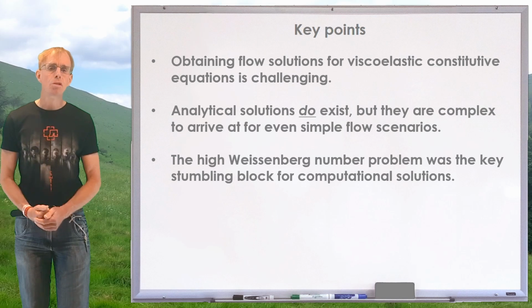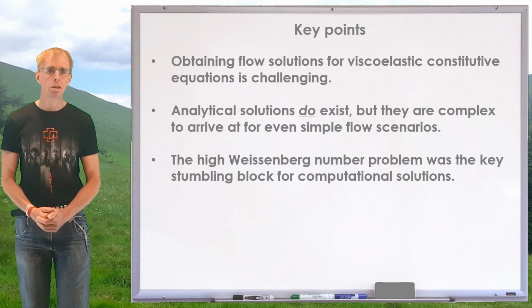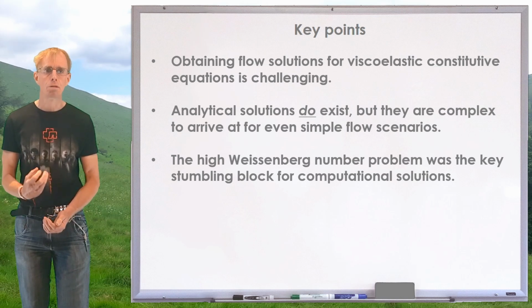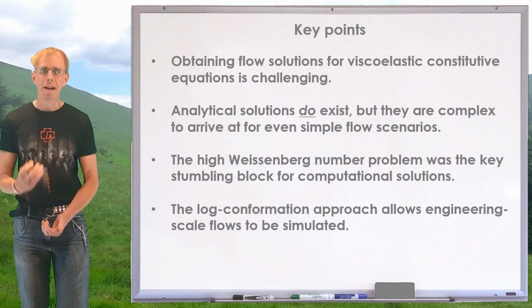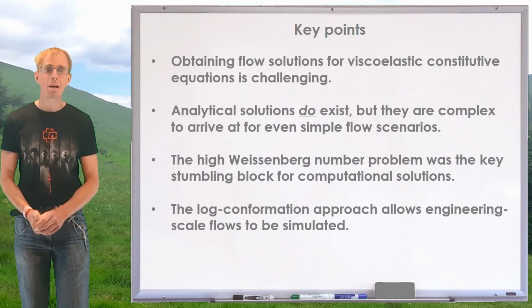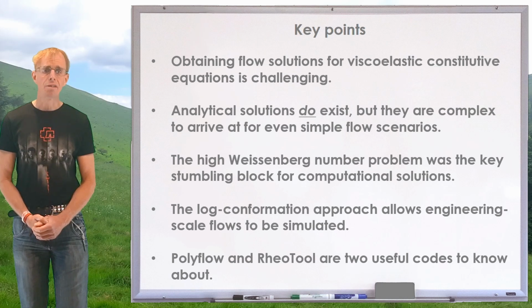One of the key numerical problems you need to be aware of, especially if you happen to find yourself using older codes, is a high Weissenberg number problem. The codes will work for slow flows and certain relaxation spectra, but you may find for the problems that really interest you, the high Weissenberg number problem is a sticking point. However, the thing to look for is log-conformation formulations for constitutive equations, because that overcomes the high Weissenberg number problem and does allow engineering scale flows to be simulated with real material responses. Two codes that you might want to look at: Polyflow with Ansys and RheoTool, part of OpenFOAM.